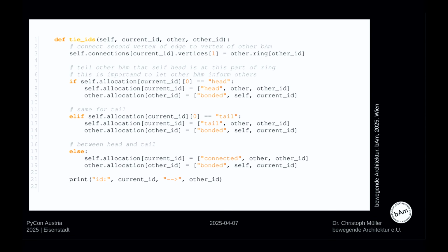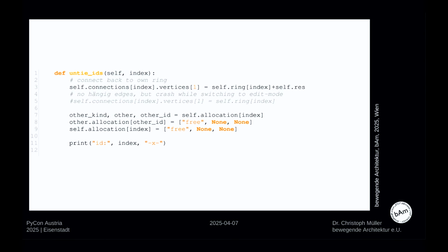Just be aware that this is a hack, so it is just a suggestion, because it's not a good idea to update a base mesh in Blender during an animation, but it's working. So basically, if you have the experience that this is suitable for you, you can do this without any errors. At least there are 2 rules that you should never break. You cannot add vertices, you cannot delete ones, and you cannot change faces. But if you only change the allocation of edges, and update the base mesh in a Blender cloth simulation, this is working.